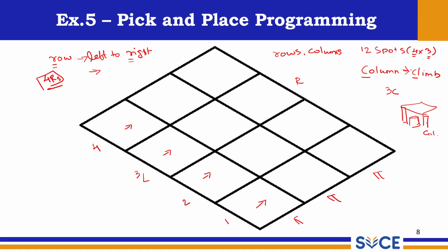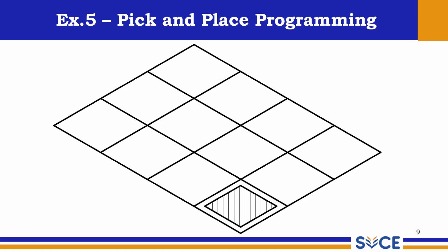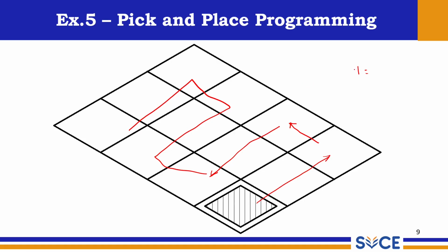Now in this robot programming, the important task is how we are going to do the palletizing part. Say this is the first space. How are you going to arrange? I wanted to arrange like this. Say number 1: from here we'll go to this part, from here we'll come to this portion like this. Clear? When you crisscross, when you come and go, this is pattern 1.